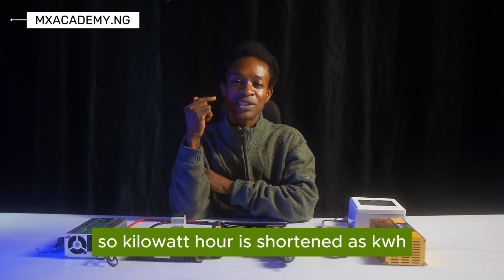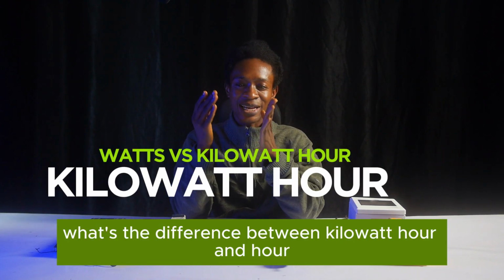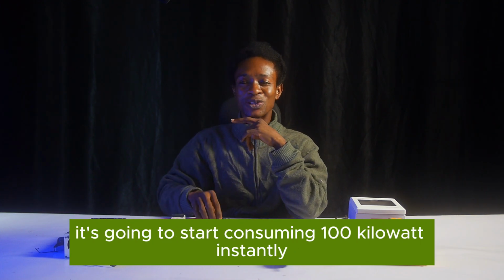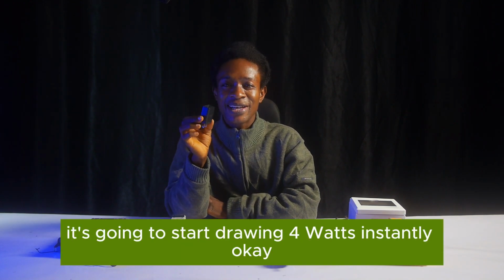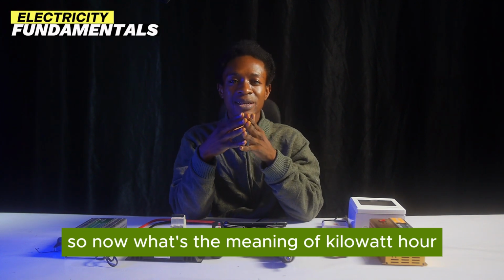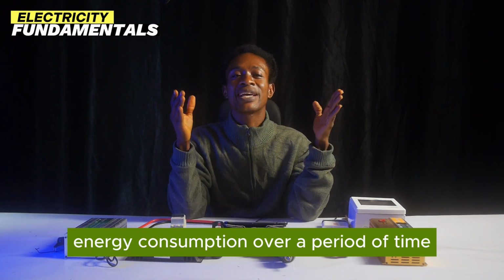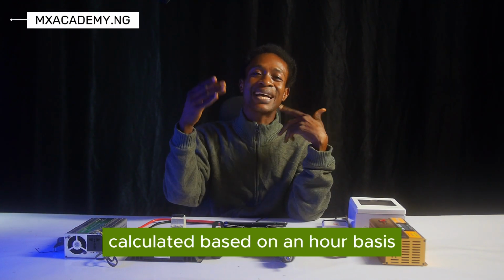Kilowatt hour is shortened as kWh. So what's the difference between kilowatt and kilowatt hour? A device that is rated as 100 kilowatt hour does not mean that if you connect it, it's going to start consuming 100 kilowatts instantly. Like I explained earlier, if you connect this small charger, it's going to start drawing 4 watts instantly. So what's the meaning of kilowatt hour? Kilowatt hour is a unit used to measure the amount of energy consumption over a period of time, usually calculated on an hourly basis.